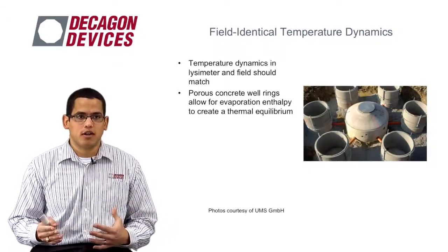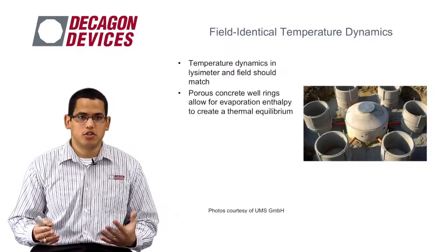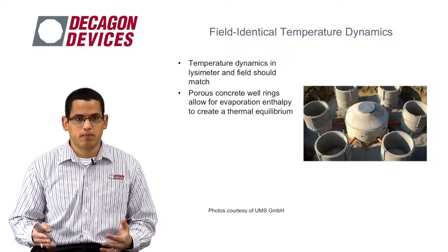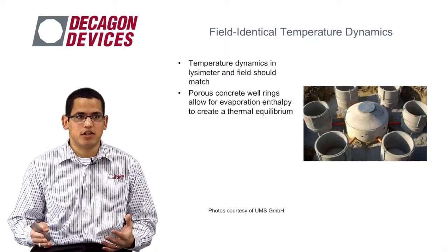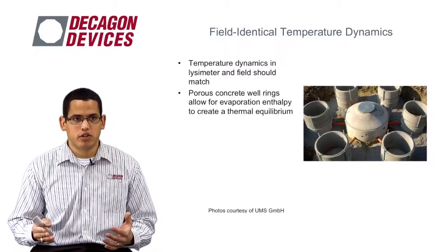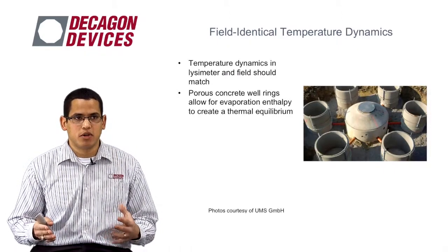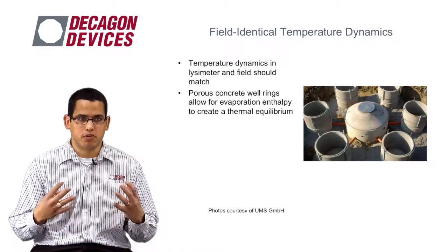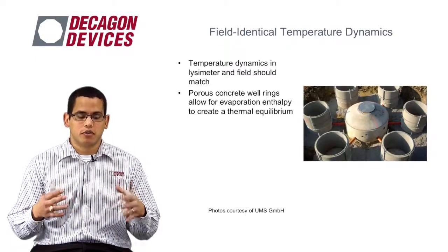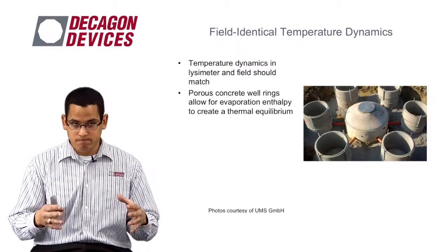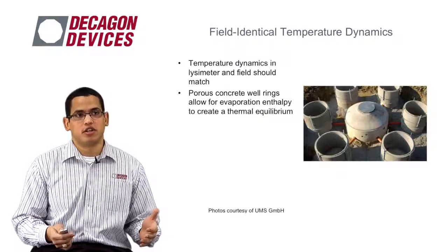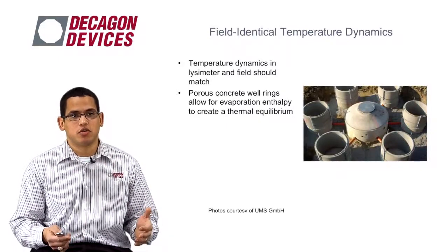So instead, a way to counteract this is to use wells that are made out of porous concrete. What this does is allow water vapor to move through the porous concrete, and by doing this we create an evaporation enthalpy within the well, matching the temperatures throughout the entire lysimeter with the temperature dynamics in the native soil.